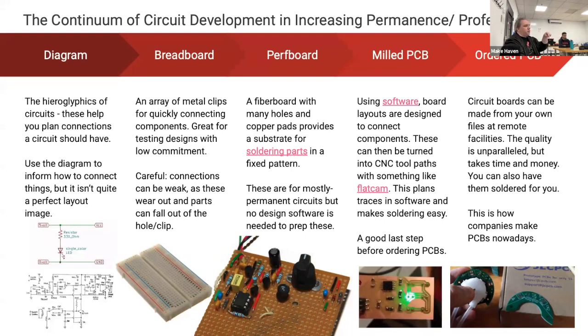And they work great for through-hole parts, which is what's pictured on there. Basically the pins from the parts go all the way through the board and then are soldered on the other side. And that holds them in place and creates the electrical connections as well. Usually, once you solder these in, you usually leave them. These are build once, and forget about it. You can adjust these circuits a little bit, but the more you solder on the parts, the more janky they get.